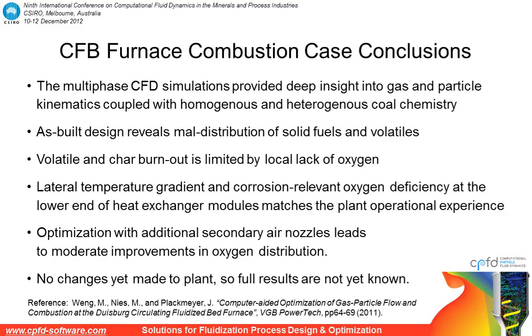So in terms of conclusions, this study showed that multi-phase CFD simulations could provide deep insight into the gas and particle kinematics coupled with the homogeneous and heterogeneous coal chemistry. The as-built case showed a maldistribution of solid fuels and volatiles, a maldistribution which actually became worse when biomass fuel was fed in at 25%. The volatiles and char burnout is limited by a local lack of oxygen.